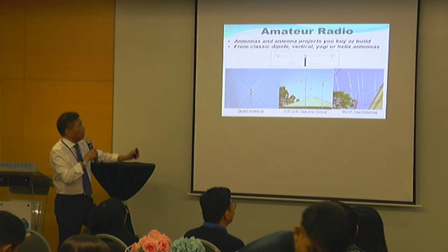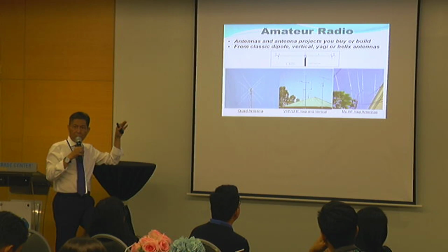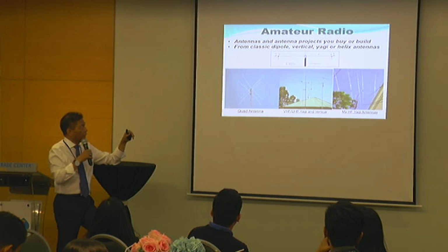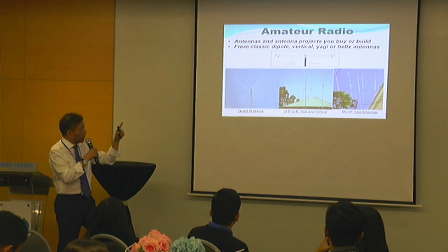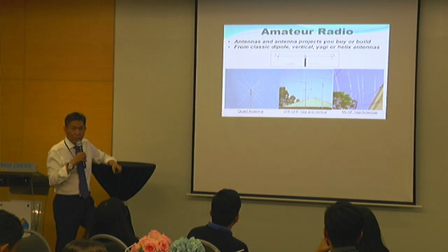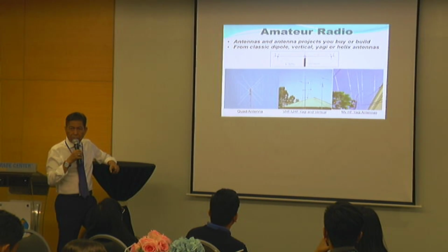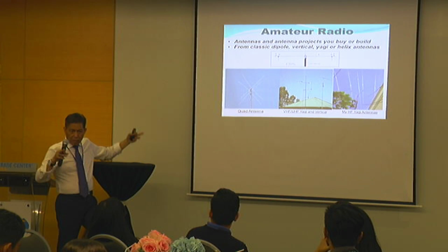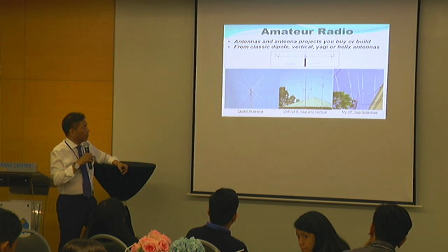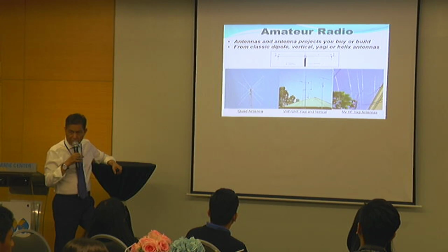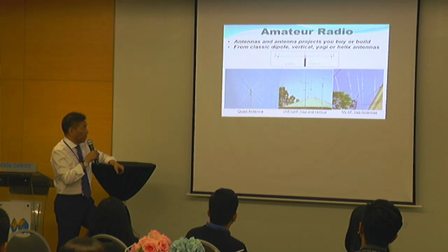And this is one facet of amateur radio that a lot of people here in the Philippines like. They like to build antennas. Okay? You could build a dipole antenna, which is on the top part of this slide. It's very simple. You need 2 wires. Connect it to a coaxial cable, make sure it's the right measurement, and you have an antenna. Or you could go quad antenna right there, lots of wires, right? But it's a very, very powerful antenna.